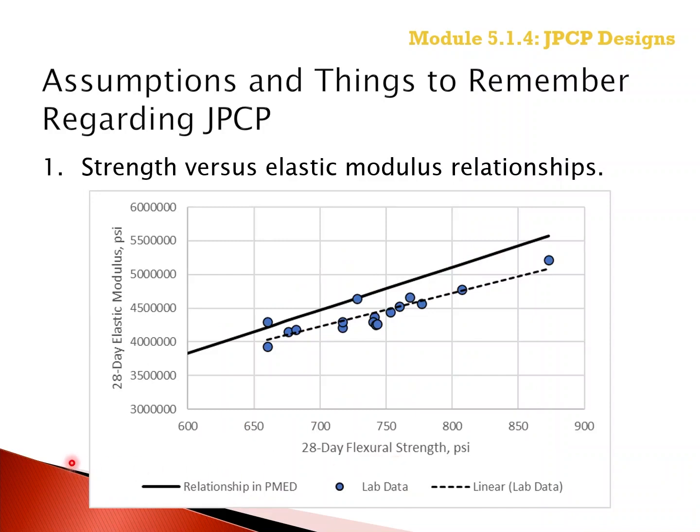This slide illustrates that the measured laboratory strength versus elastic modulus can deviate from the standard relationship or regression equation between strength and elastic modulus embedded in the software, which was presented in Module 4.4.4 on PCC material properties inputs.